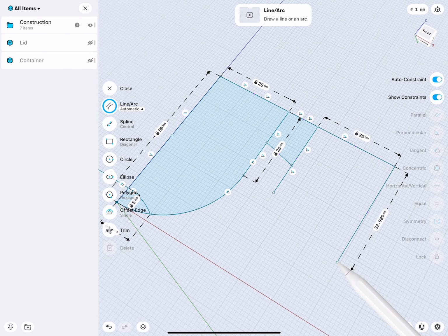Here we want to actually extend this a little bit. So I moved this by 1 millimeter, you see. Now I can select both faces or just one face. So it's 1 millimeter left and right. The reason why I did this is because now it sits actually right inside the wall, but it does not go through it. Maybe here, this top, I moved down by 1 millimeter.